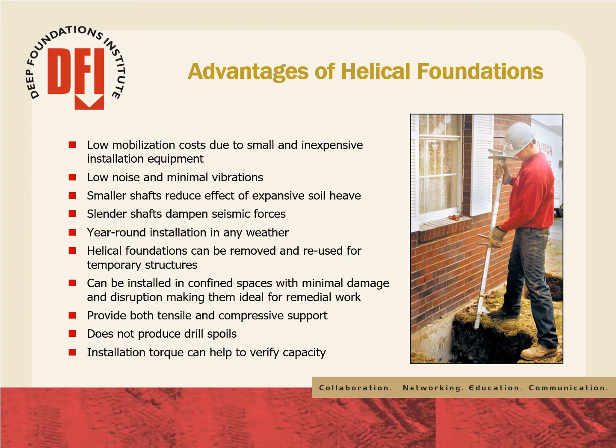This slide lists several of the advantages available with helical piles. Some of the major advantages include low mobilization cost due to small and inexpensive installation equipment, low noise and minimal vibrations, year-round installation in any weather.